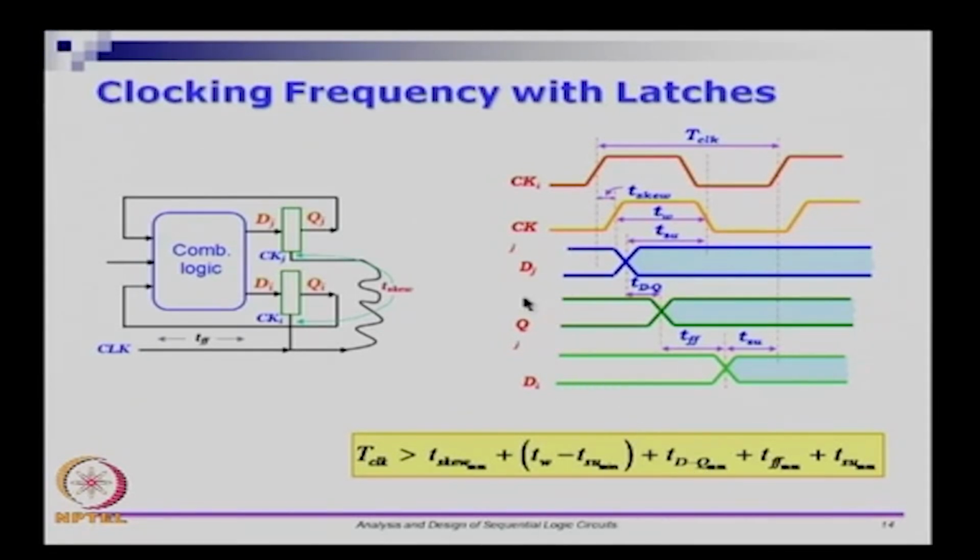So we are looking at Di input with respect to Qj, but we cannot do it with respect to just Qj, because it is not just that Qj is changing Di. If the clock is on, if Dj changes, Qj can change, and if Qj changes, Di will again change, right. We want to ensure that there is this chain of events, Dj to Qj to Di, we want to control all of that. That is why we have done it in this way.